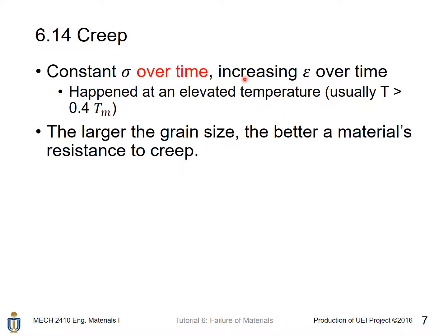For example, if you pull a bar and hold this force for a prolonged period of time, even if the applied stress is well below the yield stress of that material, the length of that material could still increase over time. And this will happen usually at temperatures higher than 0.4 times the melting point of that particular material.